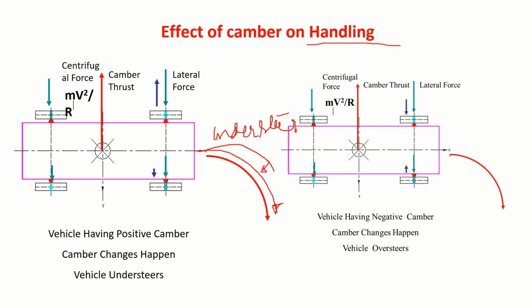Correct. Suppose I have to steer less, because instead the vehicle takes a turn like this. Then I call it an oversteer condition. With too much understeer, I need to put in a lot of effort to make the vehicle follow the desired path. With oversteer, without putting in much effort on its own, it might turn dangerous. So we need to be careful.